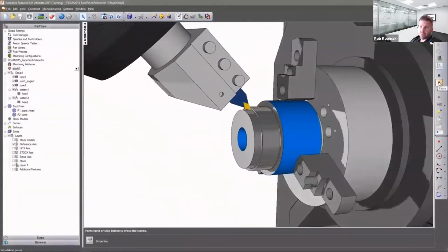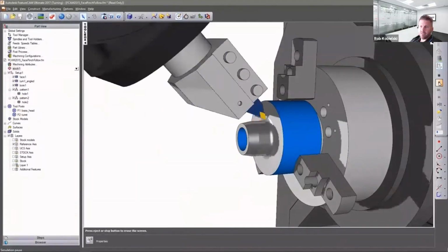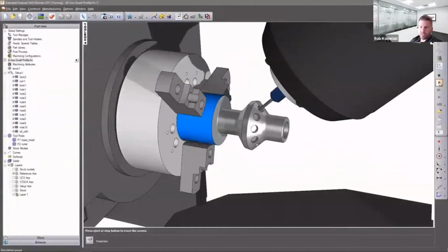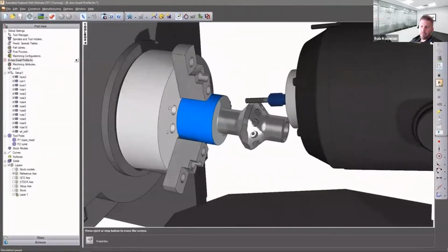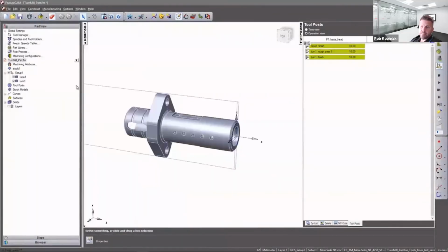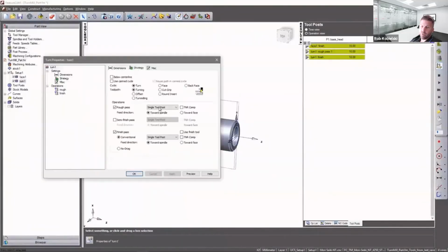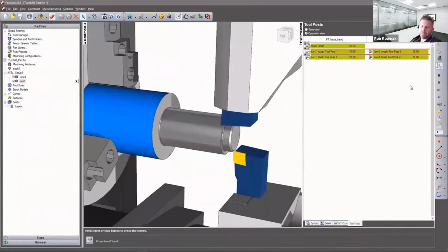Advanced tool holders, such as mini turrets and multi-tool blocks, enhance the tool capacity of your machine and reduce the chance for tool changes. For machines with indexable heads, fixed and B-axis turning is supported to improve clearance and minimize witness marks. The B-axis can also be used for angled features and full 5-axis simultaneous milling.